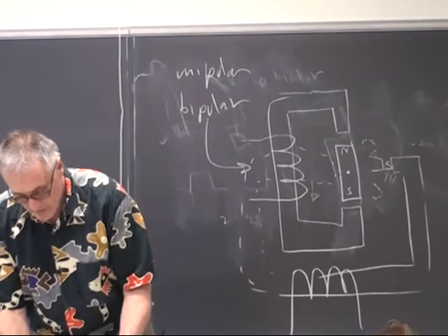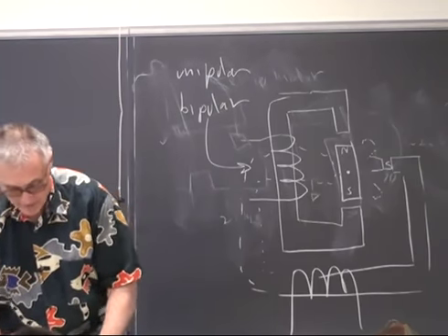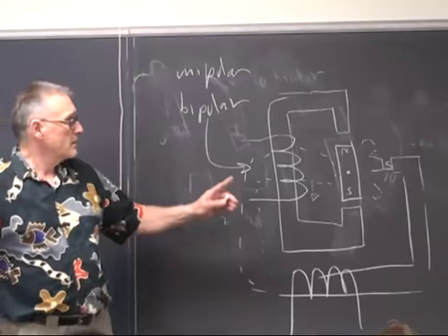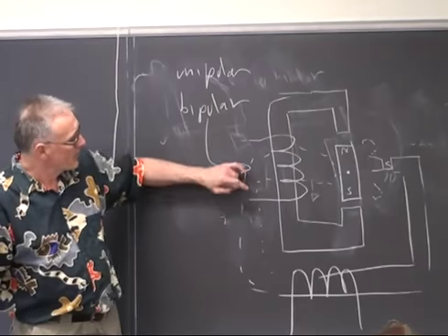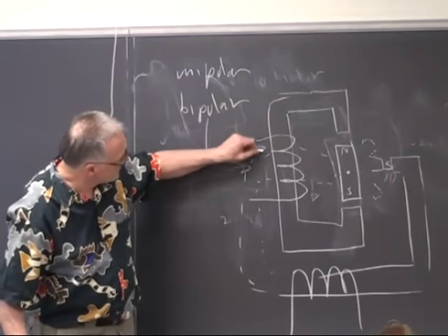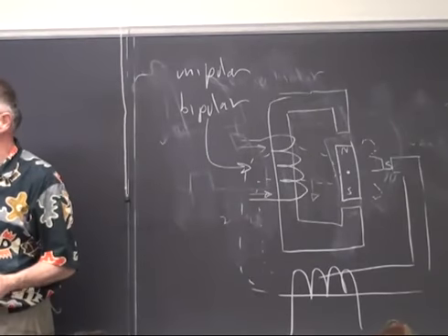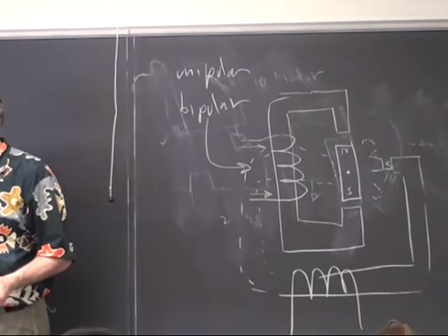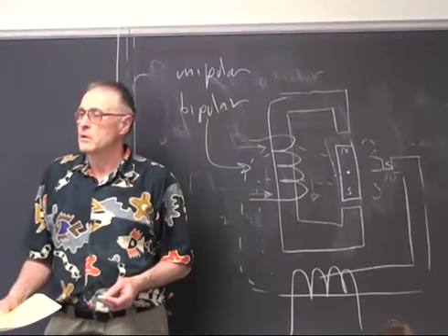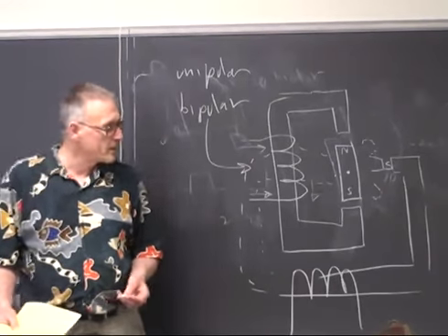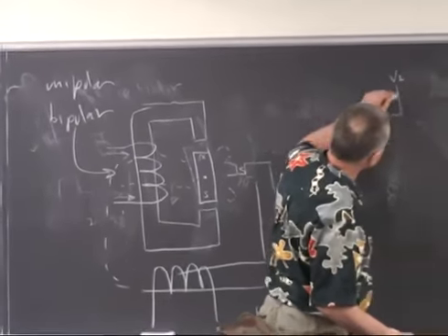And there's all kinds of drive schemes. But first of all, let's talk about driving the current here. You want to be able to drive a current either through the coil this way or through the coil this way. You typically want to use only one voltage source, not a split voltage source. And this implies that you have to have a switching setup that will route current in one of two directions through two leads. And what is typically used is a switching setup that looks like this.